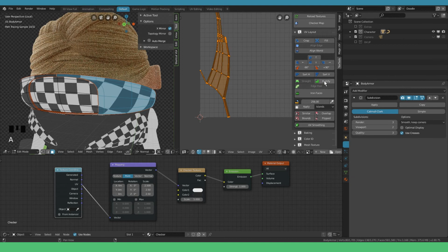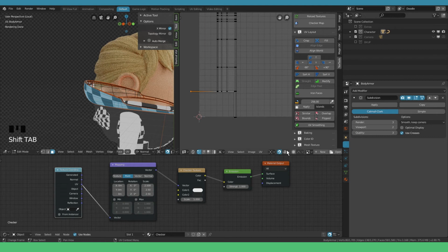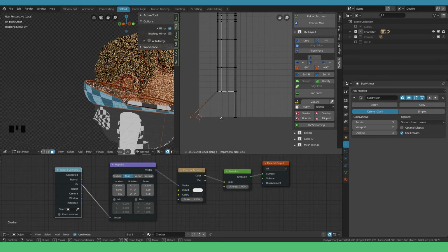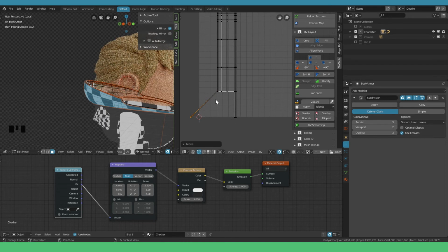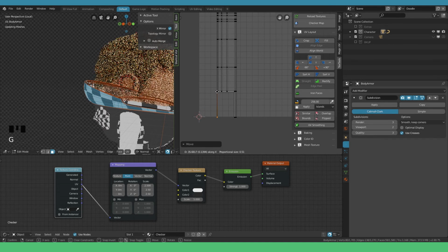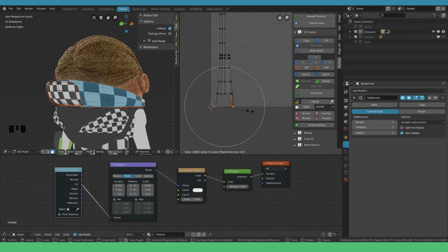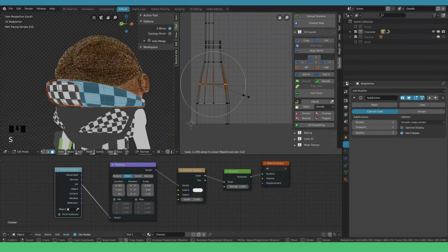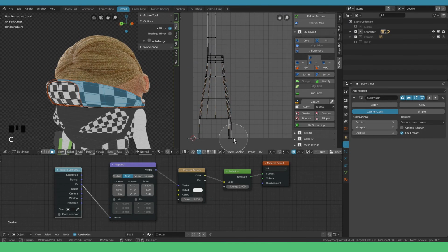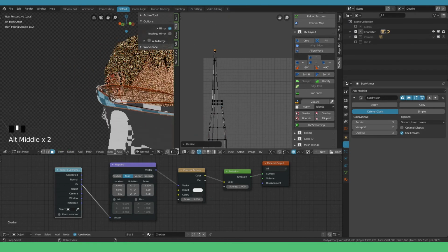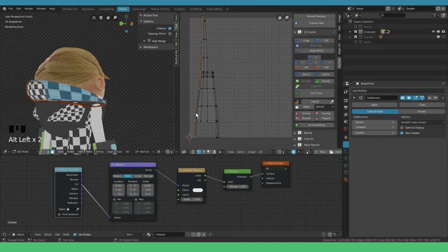To clean these stray vertices, I'm gonna use snapping. Enable snapping down at the bottom and set the snapping to vertex. Snap to this vertex while constraining the y-axis. After that, snap this vertex while constraining to the x-axis. Now I'm gonna use proportional editing to scale up the back. Bring the vertices in on the front part of the mesh. I'm gonna straighten out the UVs again.